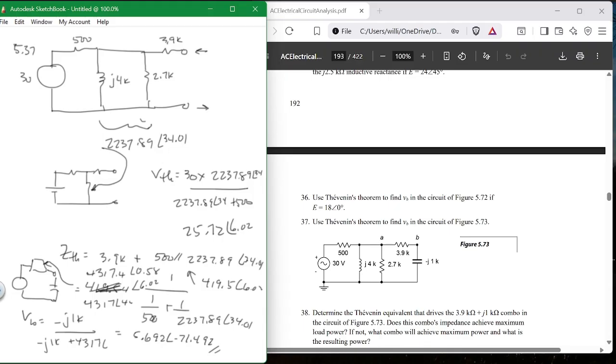If you work in a factory, if you work in an industry, they will say, design a motor starter center. And you go through and you put all this stuff together. Then they'll say, did you add the capacitors? And if you give them a look like, why do you have to have capacitors? What does that mean? Oh, you didn't take a course where you had to do this stuff. That makes sense? This explains why you have to add capacitors in order to make your motor currents the least, bring them down to the minimum, to where you're getting the bang for your buck.